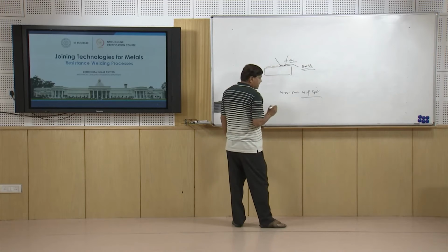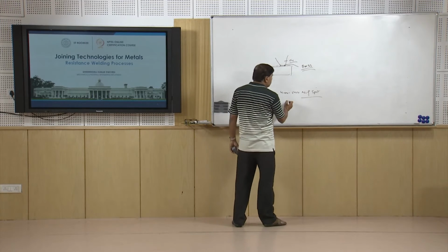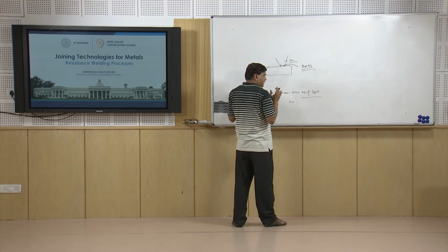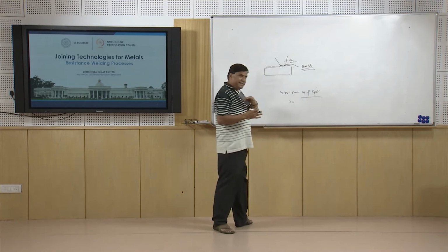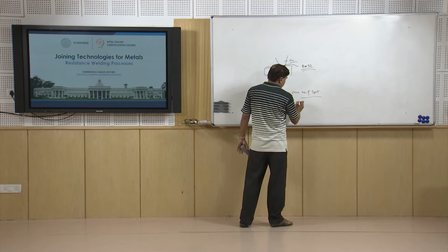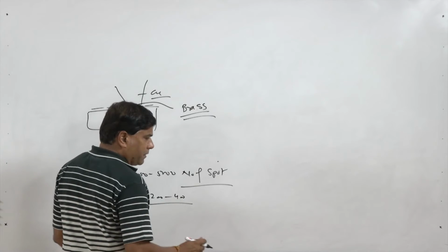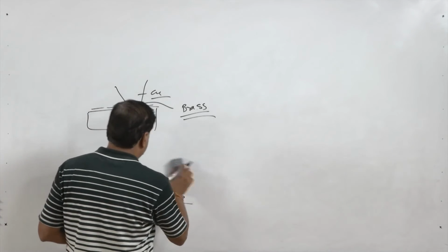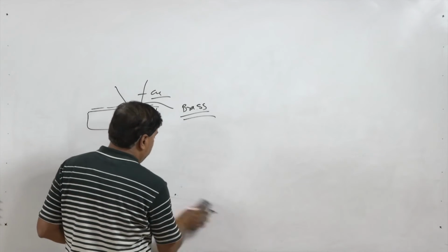When zinc coated steels are spot welded, you may find that after about 200, the diameter gets enlarged to such an extent that it needs replacement or refurbishing, so that the same size of nugget diameter can be achieved.